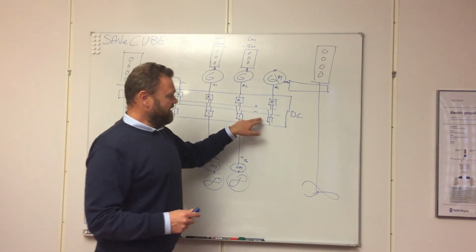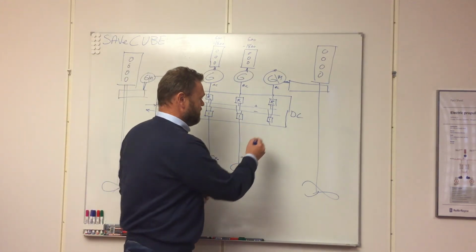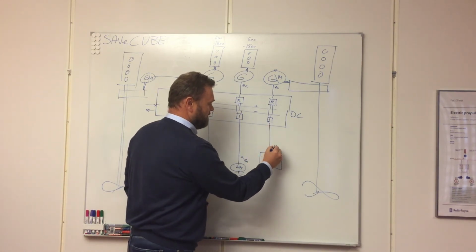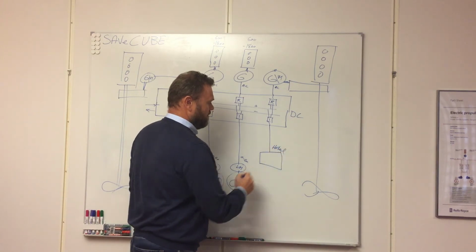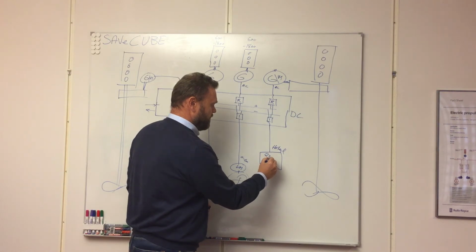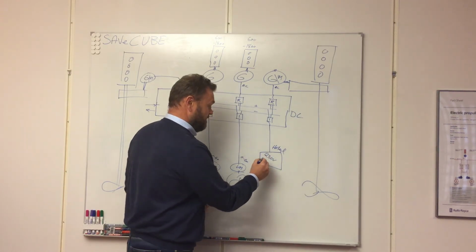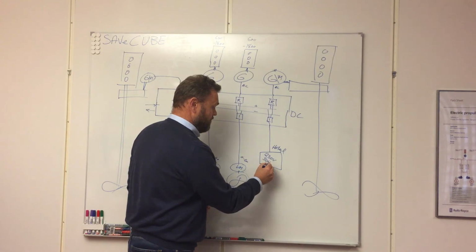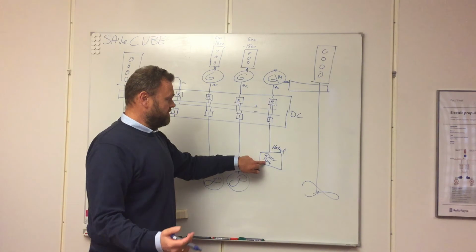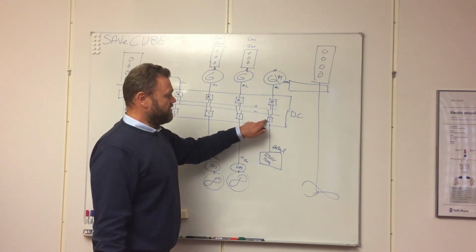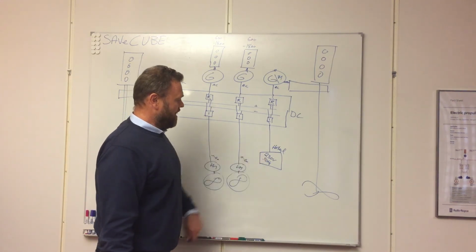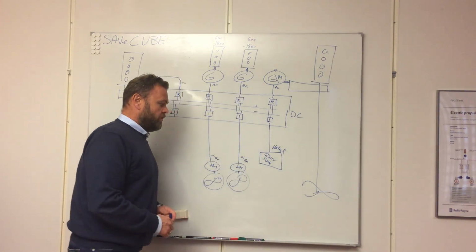So you need an inverter to make your switchboard for the hotel load and to have a stable 230 volt, maybe 50 hertz. You can pick and choose whatever frequency you would like to have, 60 or 50, because we have an inverter, so we produce the frequency and the voltage you would like to have out on the hotel load.